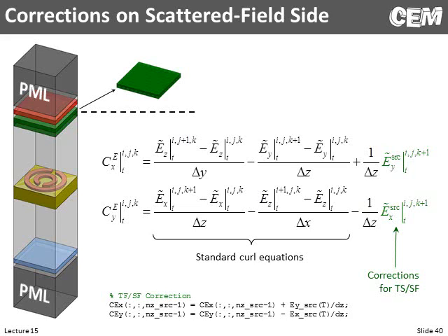Remember how we isolated the curl equations, and here's one big reason why. The terms that reach across the interface are completely in the curl terms. So in fact, we can implement the source in the calculation of these curl terms and not have to worry about messing with the other big update equations that we just calculated.